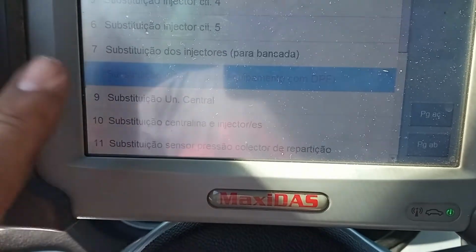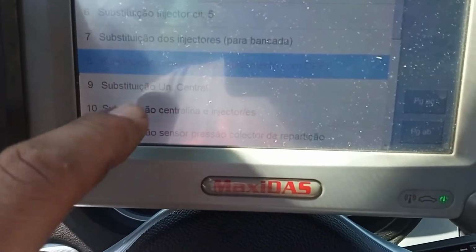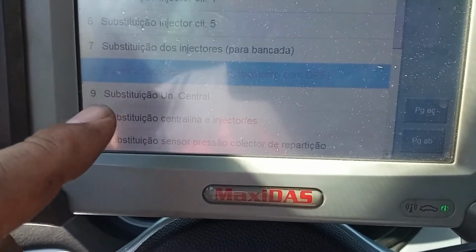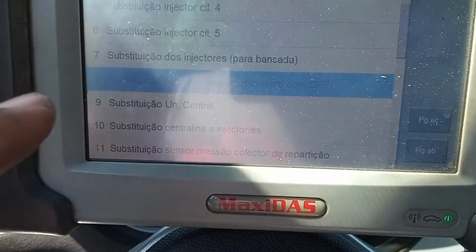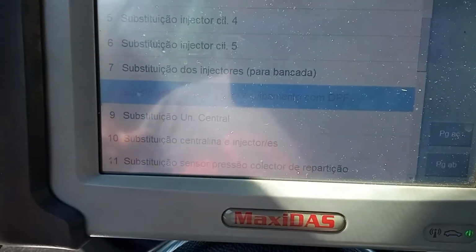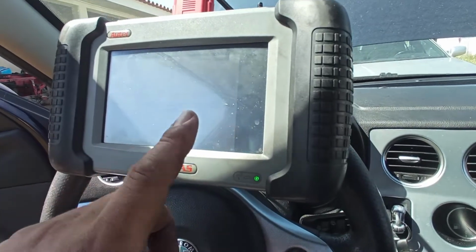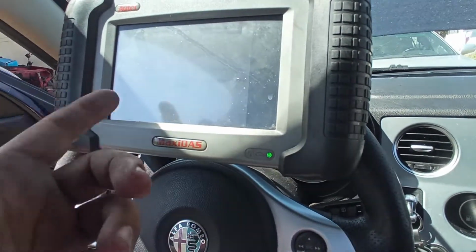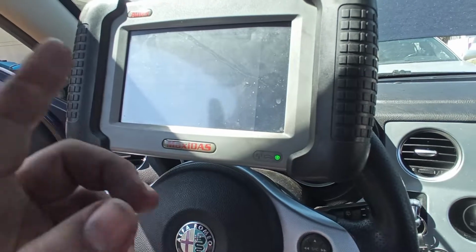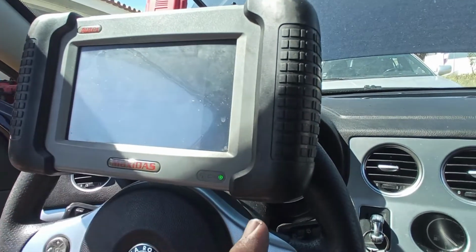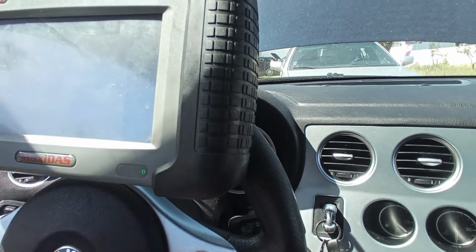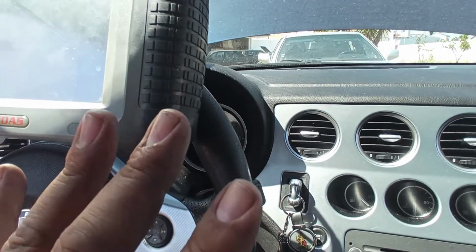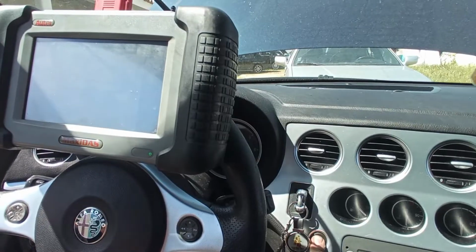After this, it is the same procedure as I did here on the oil, okay, to do the other stuff. After that, and only after that, we will see the live data to see how things are, okay? For the replacement of the DPF, it asks for the engine start because it wants to see the back pressure, okay? Very clever. And it is the first time that I will start it, and it can have a rough start because of all of the stuff that I did on the engine, okay? So don't be scared if the start is very rough.